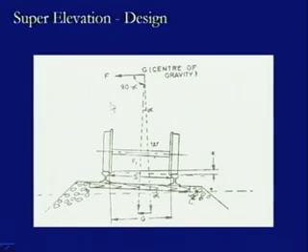Therefore, when we take the resultant of this centrifugal force F and the weight W which is acting in downward direction, then this resultant will be acting likewise at an angle alpha with respect to W, and this is what is defined. So, if this is working in this form, then this remains within the wheel base condition, and this is the equilibrium condition being achieved. And in this condition, the weight or the load which is transferred through this wheel or the load which is transferred to this wheel, they are same in nature.